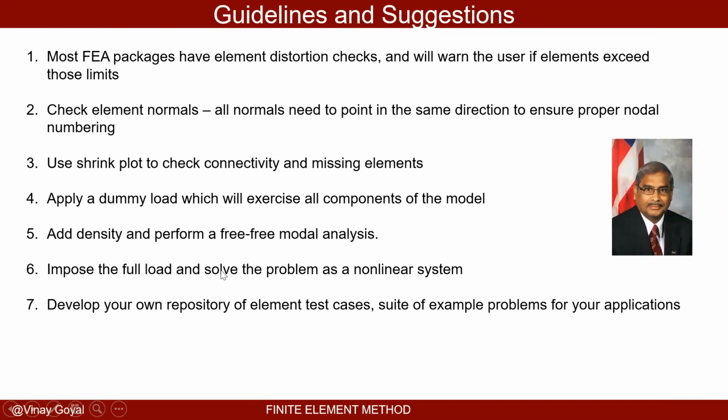Okay, guidelines and suggestions. Most finite element packages have element distortion checks and will warn the user if the element exceeds these limits. Check the element normals. All element normals need to point in the same direction to ensure proper nodal numbering. Use shrink plots to check connectivity and missing elements. You can do all of this very quickly these days.